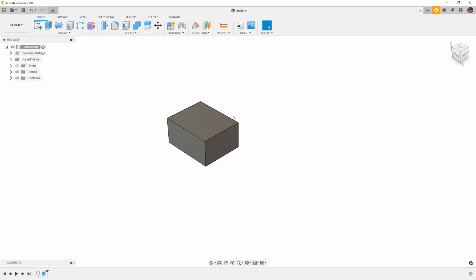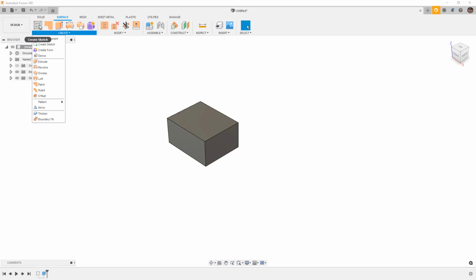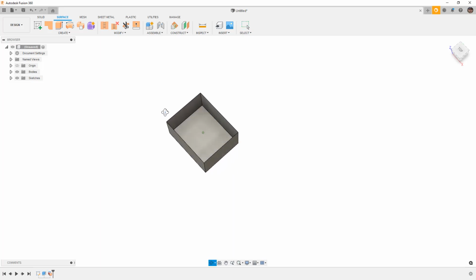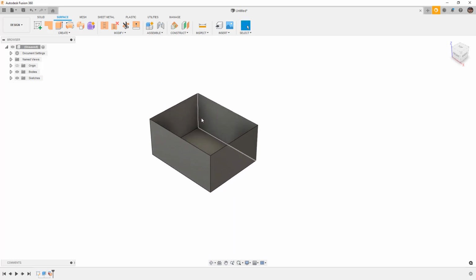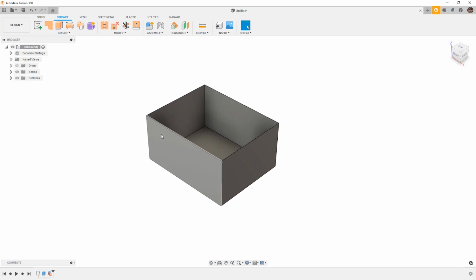When we talk about creating surfaces, the workflow is extremely similar. We typically would create sketches, and we would do things like extrude, revolve, sweep to build them into 3D. Since we're on the surface tools, I'm going to just simply delete the top face of the solid, which automatically converts it to a surface. A surface is just a face representation, but these are still considered B-reps. We can use these surfaces to cut solids, replace solid faces, or we can turn them into solids themselves.